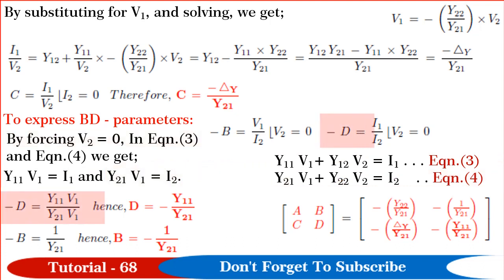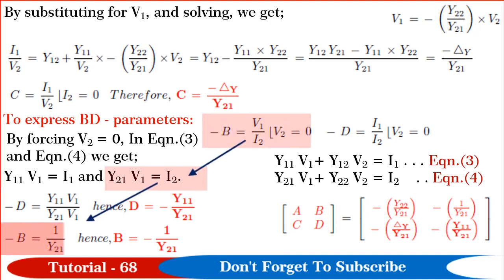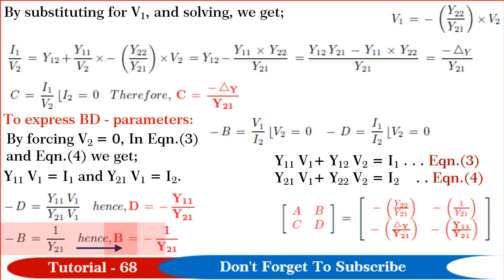Hence, minus D is equal to Y11 V1 divided by Y21 V1 and hence D is equal to minus Y11 divided by Y21. Similarly, minus B is equal to 1 upon Y21 and B is equal to minus 1 upon Y21. The ABCD parameters so obtained are indicated here.